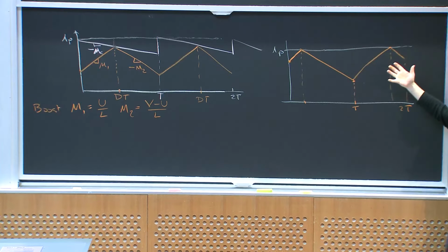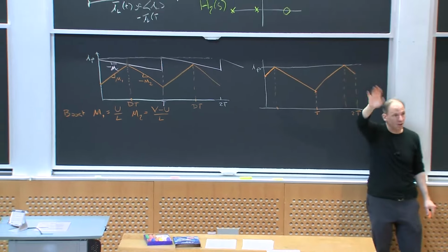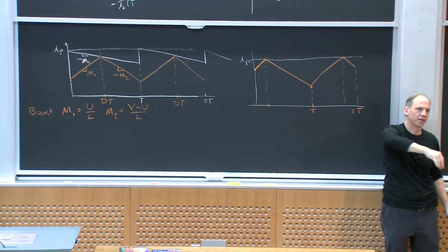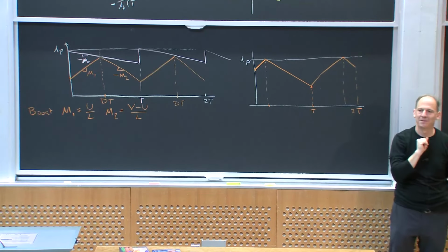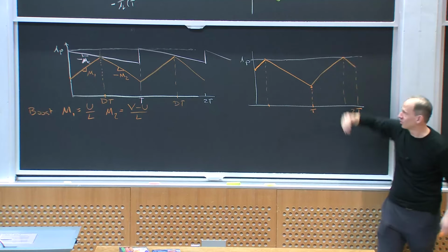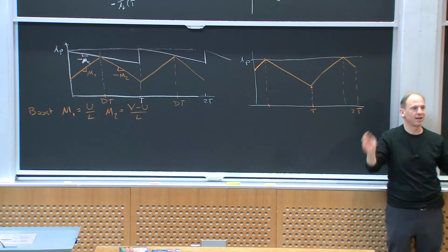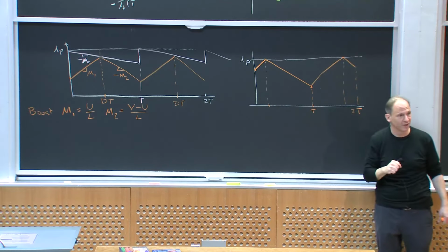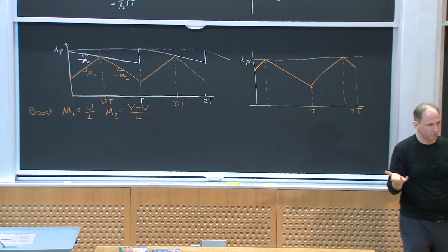In some examples, it won't settle down at all. It'll just bounce around chaotically. I mean, literally chaotically, okay? Now, is that a problem? Well, at the highest order, it's not. I'm still controlling the peak current. My output loop will still regulate and everything. But it is problematic from other perspectives.